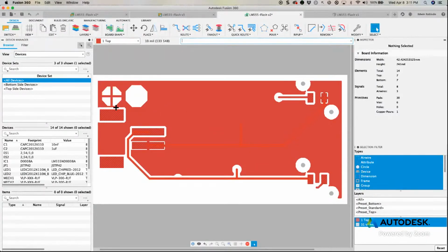It could be out of plastic, or sheets of metal as well. This process is usually used if you have a reflow oven. You put the stencil over your board, cover it with solder paste, put your parts on the board, and then put that in the oven. Usually it takes around 7 to 8 minutes to get your boards baked and all your components soldered to the board. So that's what that value actually controls.